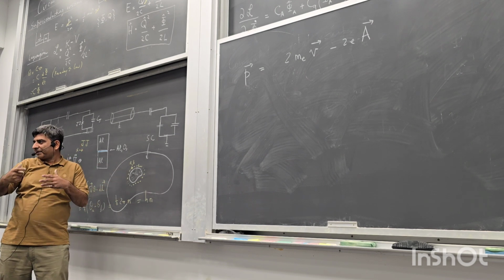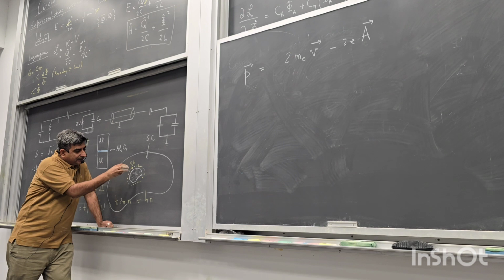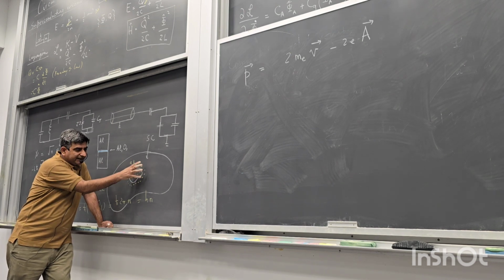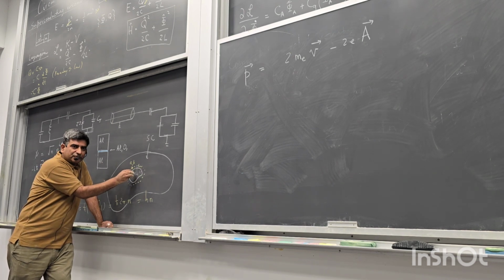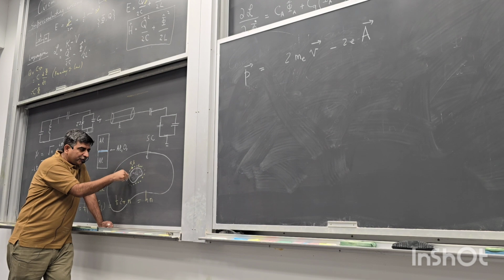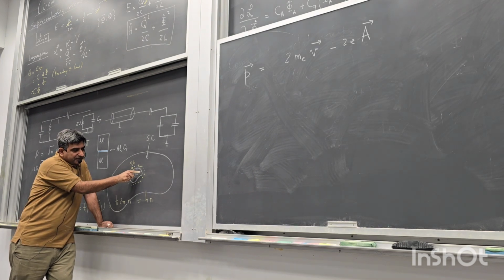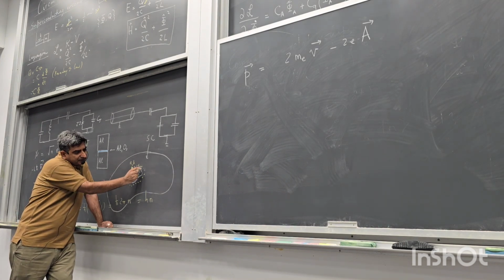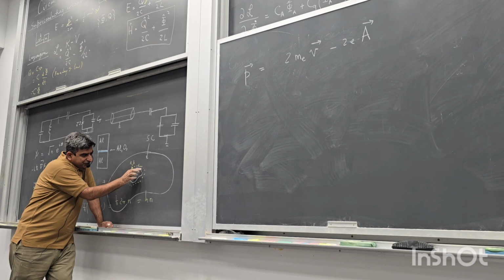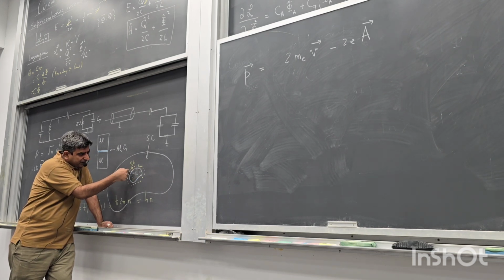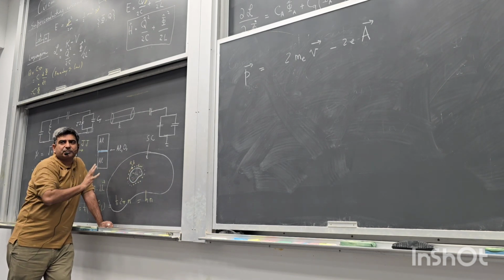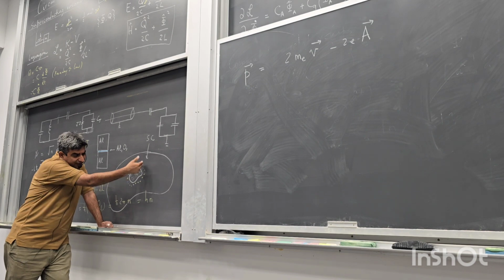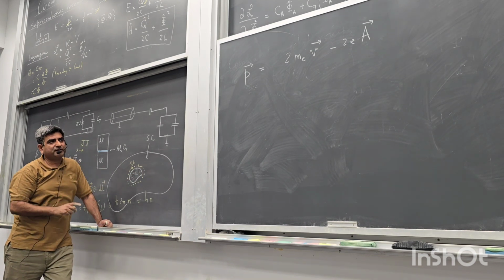In fact, this is called the Meissner effect. So there will be no flux inside the conductor, only flux through the hole, which means circulating currents are produced just on the inner periphery, and there will be some skin depth over which currents will produce, but we assume that our contour is far away from that skin depth. So there is no current inside the superconductor.